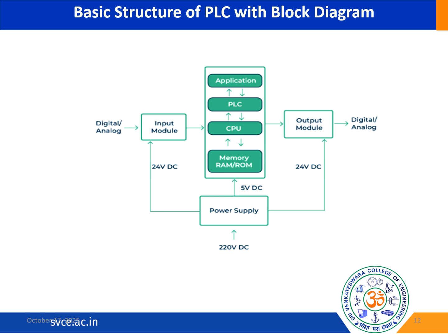When you consider the main controller, the controller sends the signal to the CPU and then it starts executing its program from the memory. After all these processes are over, the program creates an instruction signal which goes to the output module. The output module receives the signal and sends it to the external device like a motor, valve, etc., which will execute the instruction by controlling the system accordingly. This part continues in a loop cycle. For one cycle, this whole process is called the scan time of the PLC.